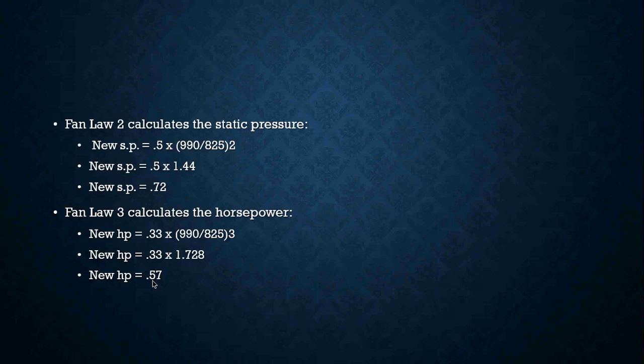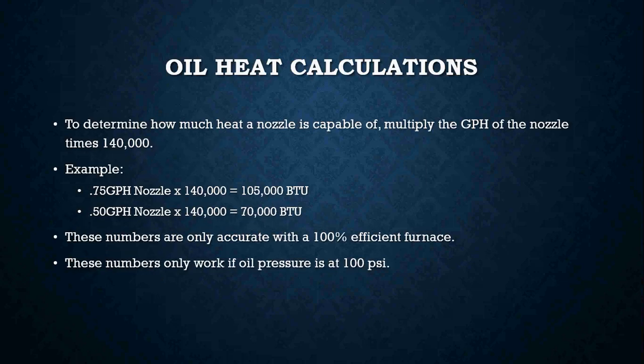I can either raise it or I can lower it, depending on what I do to my fan speed, what I do to my ductwork, whether I'm adding a zone or extending ductwork or removing ductwork or whatever the heck it is that has to happen. You are going to adversely affect the performance of those components.